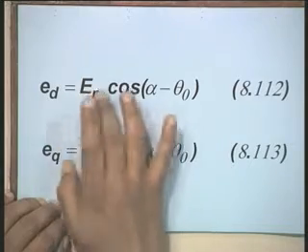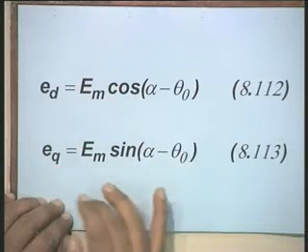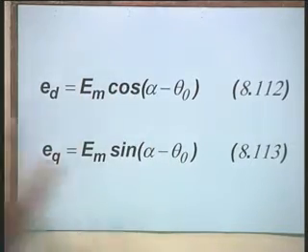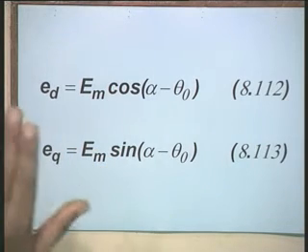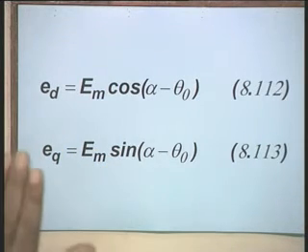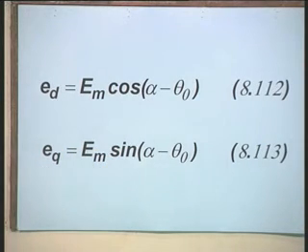Now, if I want to express any quantity in terms of this, then it is expressed in terms of the peak value. If I have chosen the stator base voltage as the peak voltage and want to choose the base voltage in terms of RMS value, then it is automatically going to be the base voltage, which is the peak value, divided by root 2.